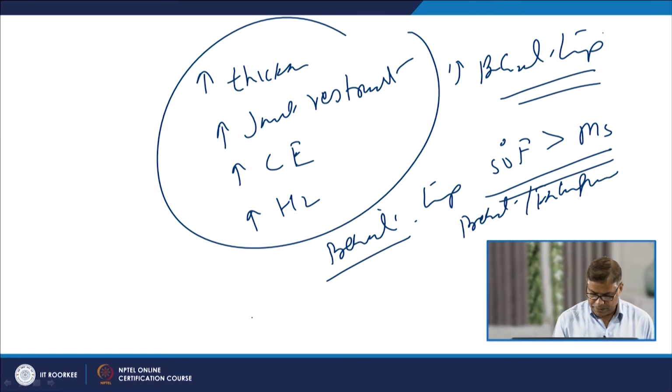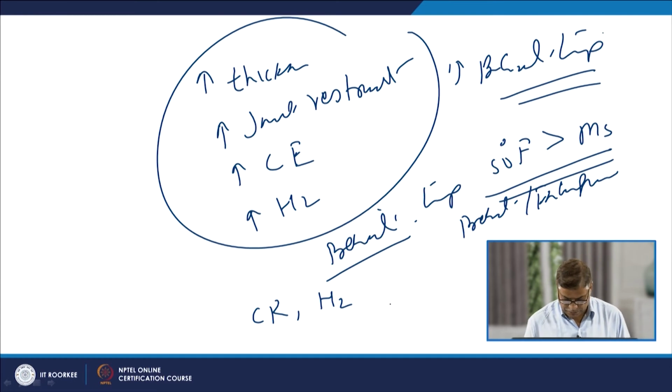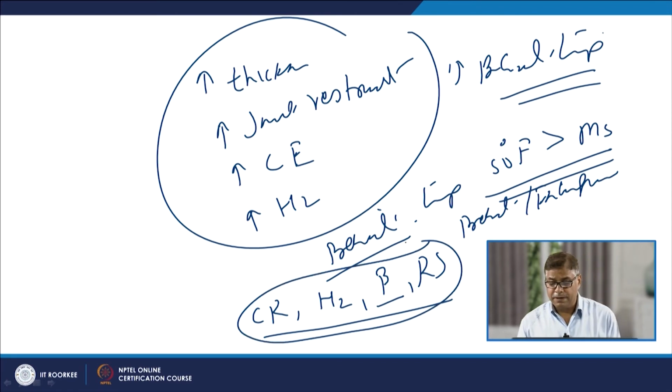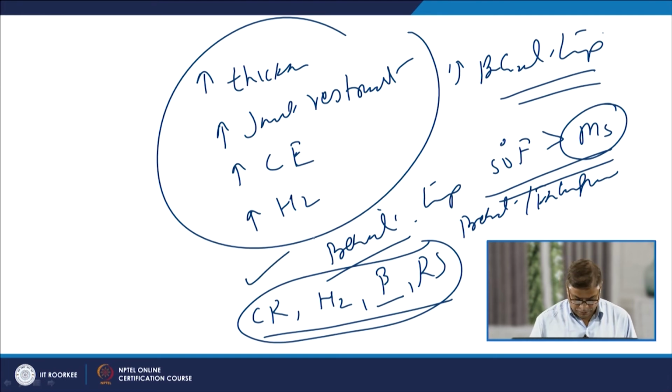When the higher temperature is given, it will reduce the cooling rate, it will permit the escaping of the hydrogen, it will permit the formation of soft phases like bainite, and it will reduce the residual stresses. So, the preheat about 50 degrees Fahrenheit greater than the MS temperature, or martensite start temperature, will lead to all the favorable benefits.